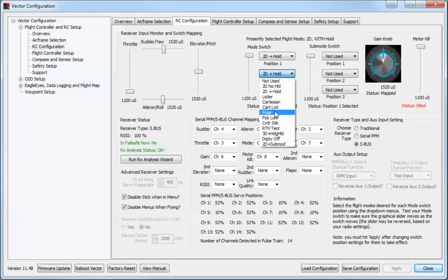Now, there are some things that you need to be aware of with this. The yaw of the aircraft is still going to be controlled by you. That is to say, let's say you went out to your 100 feet away and you turned the yaw round so the camera is now facing you. If you purely use the aileron to move left and right, the multi-rotor will not yaw itself around to automatically point at the home point. So while the aircraft is flying around this circle, the actual yaw of the aircraft will not follow the inside of it. So you do still have to control that element of it. However, with a little bit of yaw adjustment you can follow that circle, and if you put an object inside that circle then you can follow it with your camera, which can be quite useful.